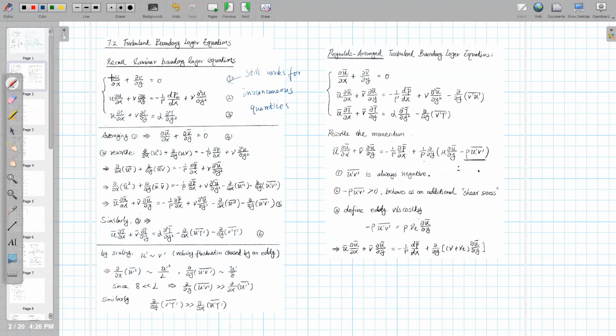This is still the governing equation for the instantaneous value of u, the instantaneous value of v, the instantaneous value of pressure, and the instantaneous value of temperature. To obtain the Reynolds averaged governing equations, you just need to write each instantaneous value into two parts: u becomes u mean plus u prime, v becomes v mean plus v prime, and temperature becomes temperature mean plus temperature prime.